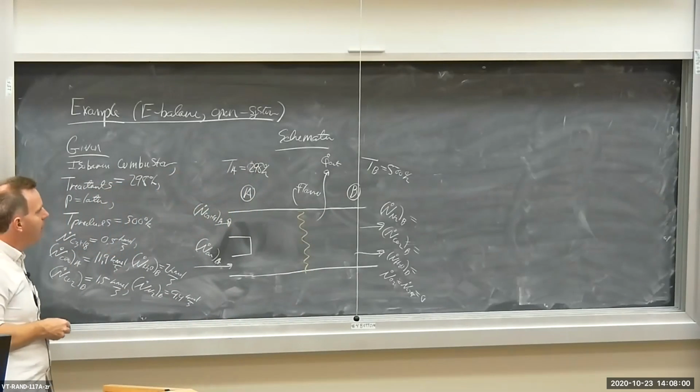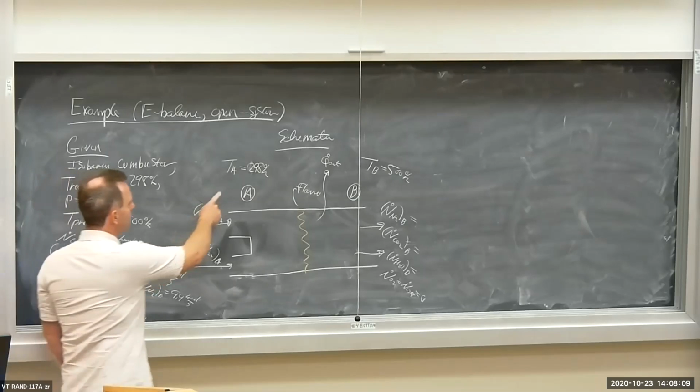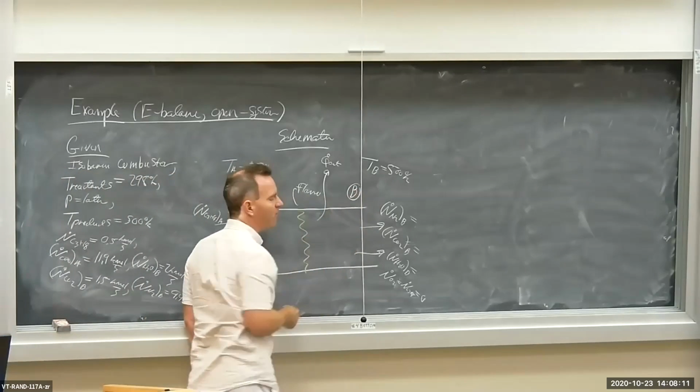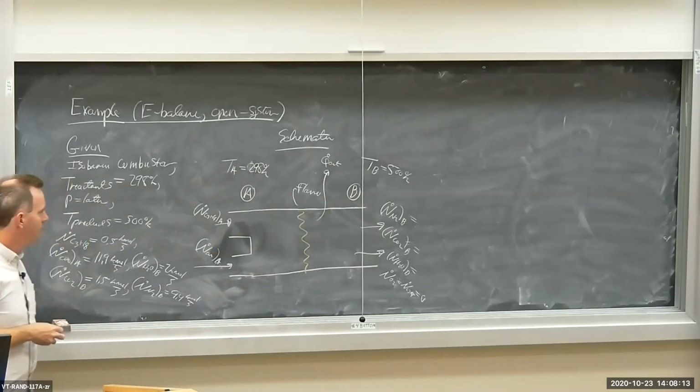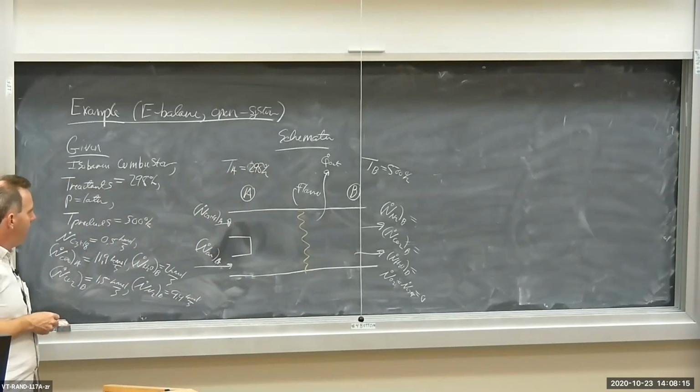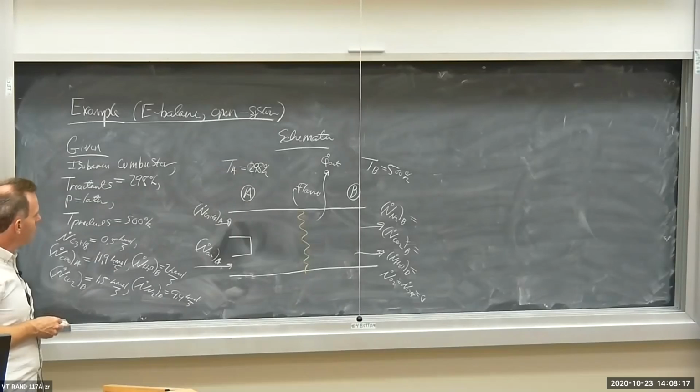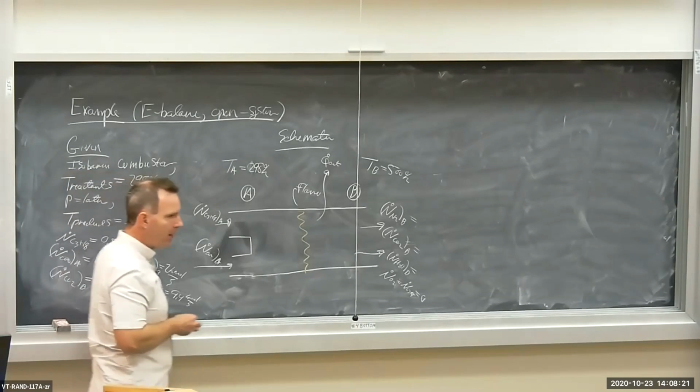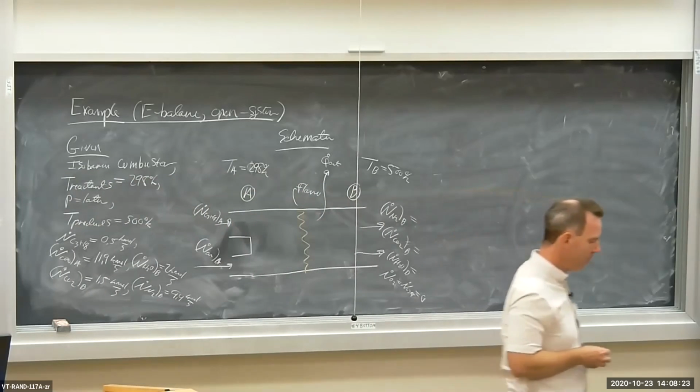You're going to release heat due to the presence of the flame, so we're going to get a Q dot out being rejected. Now, the temperature of the reactants T_A is 298 degrees Kelvin, and the temperature of the products is 500 degrees Kelvin. What's being burned here? We're burning C3H8, which is propane. It's a gas, a vapor, not liquid propane.